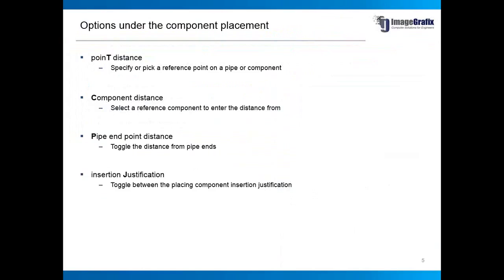And similarly, if you go for the insertion justification, which helps us to choose the insertion point, or maybe the distance reference point of the component, either from the left hand side of the component, or maybe the right hand side of the component, or the center of the component.